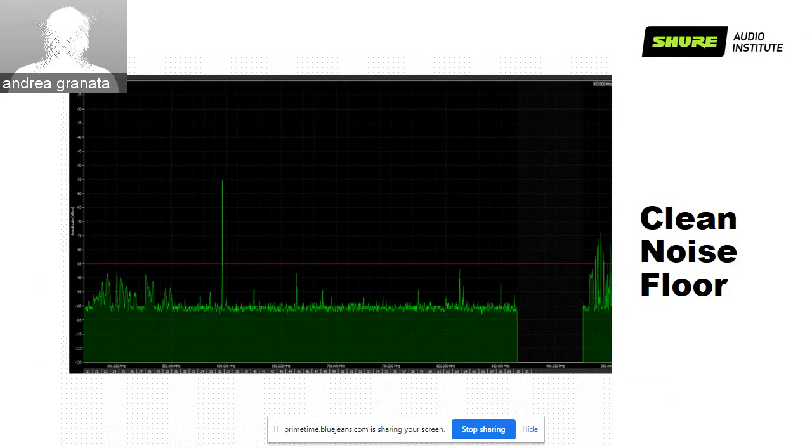As you can see, even though everything having an energy below -85 can be used, it's not all the same. In some areas, in the lower UHF around between 470 and 530, I think 550, we can see that there is much more noise than, let's say, over 600 megahertz. So the operational range will be different if we tune a microphone around 510, 515, or 605, 610. So we will have a different operating range, but both frequencies are considered good enough to be operated by Wireless Workbench.